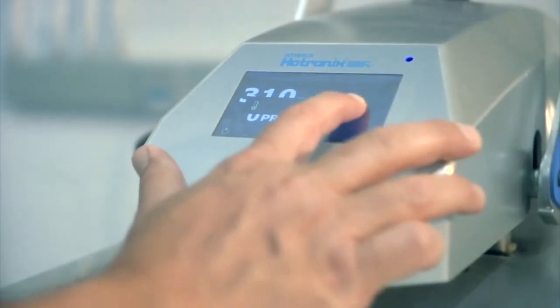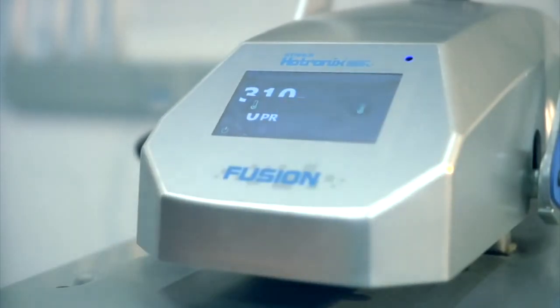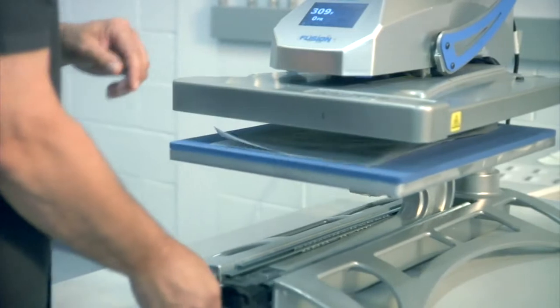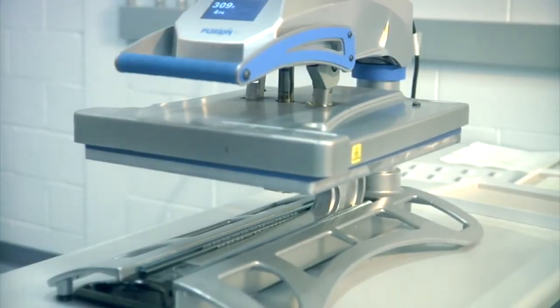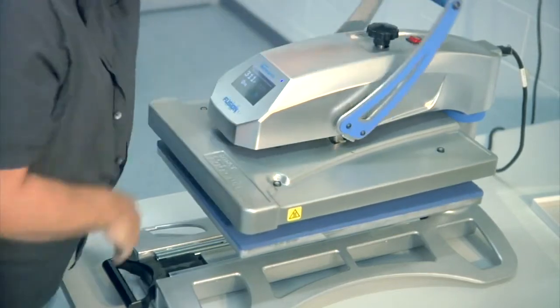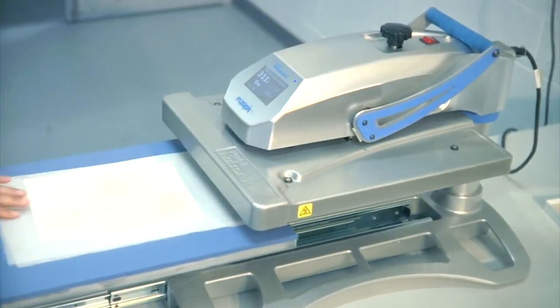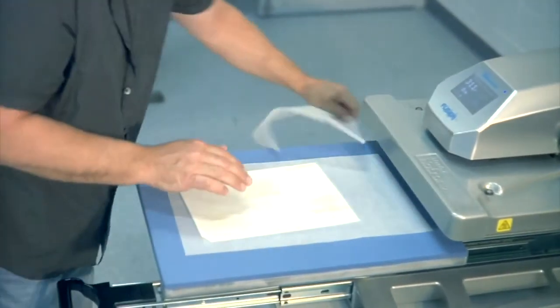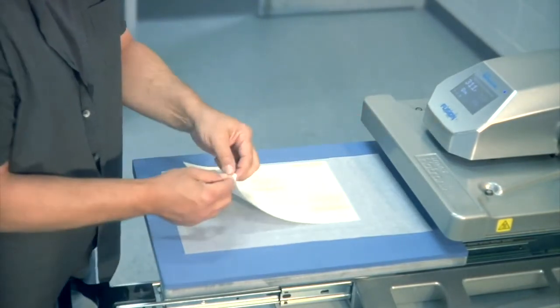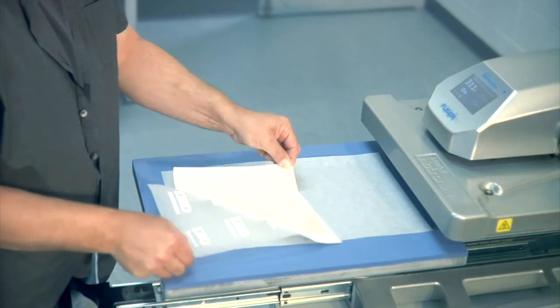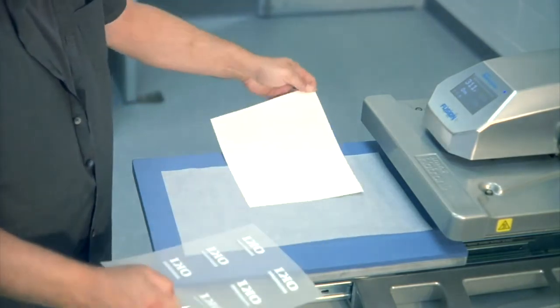Apply the recommended settings to your heat press. Once your heat press reaches the targeted temperature, begin the press. When the time is complete, open your press and quickly perform a hot peel of the B sheet using a smooth, steady motion. Next, inspect both sheets to ensure that the B sheet has completely transferred to all printed elements of the A sheet.